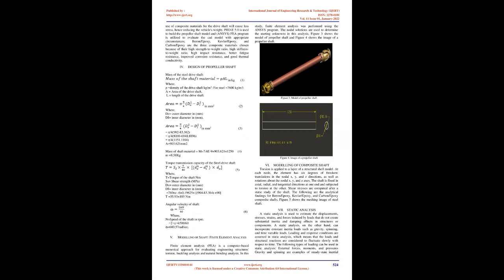The shaft was developed and analyzed using ANSYS by the authors Navin and Reddy, 2018, 13. The analysis was performed on 4 distinct materials, including traditional structural steel and 3 different composite materials: E-glass/epoxy, high-strength carbon epoxy, 230 GPa, and high modulus carbon epoxy, 395 GPa.